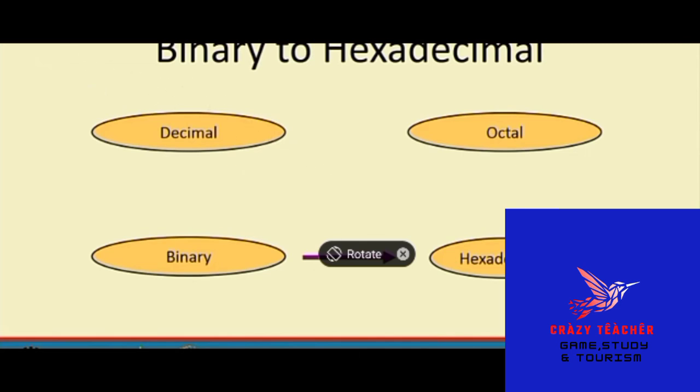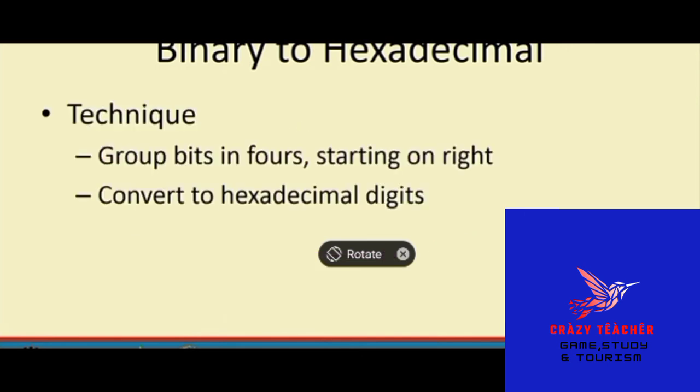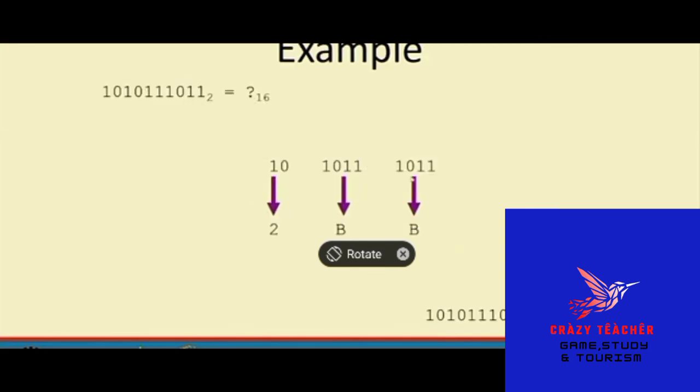So this is an exercise: 29.8. If you convert 29 into binary, this is the number. And for 0.8, if you go on multiplying by 2, 0.8 times 2 is 1.6, so you get the 1 here. Now 0.6 remains, multiplied by 2 gives 1.2, so again you get a 1 here. Now 0.2 remains. 0.2 multiplied by 2 is 0.4, so you get a 0 here. That 0.4 multiplied by 2 gives 0.8 again, so that 0 comes here. The 0.8 multiplied by 2 gives 1.6 again, and the 1 comes here. So that way it goes on. This way we can convert decimal numbers into binary numbers.